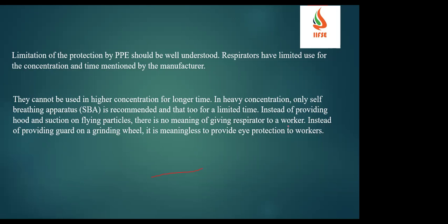It means that we should always focus on the elimination part. It is not that you have dust everywhere in the work area and you simply give a mask, saying okay, it will do. No, we should try to minimize or eliminate the hazard. As a last remedy, you should give this mask as a control or an additional measure. Instead of providing a guard on the grinding wheel, it is meaningless to provide eye protection to the workers.